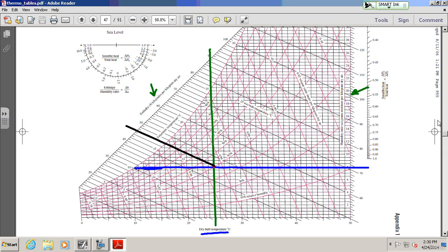And when water evaporates, it cools, okay? That's why you sweat, right? The reason you sweat when it gets hot outside is that you evaporate water, and evaporating water cools you down, okay? Well, same thing happens inside a psychrometer. The evaporating water inside the wet bulb cools.